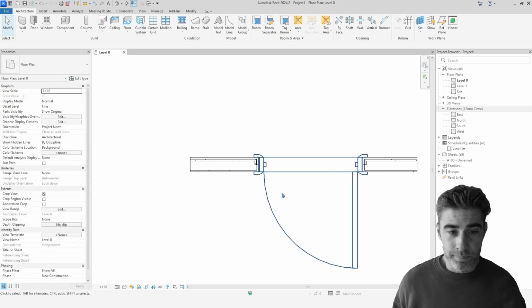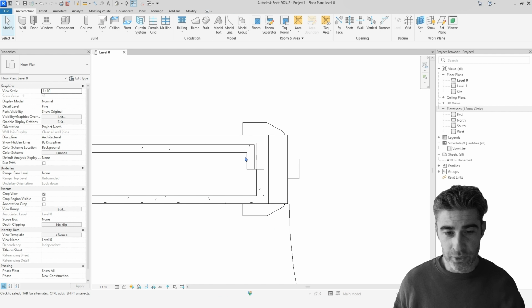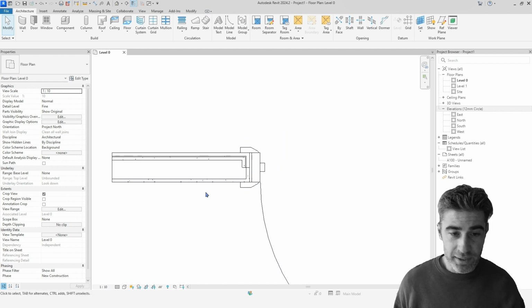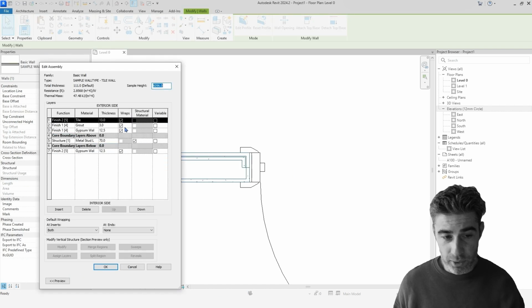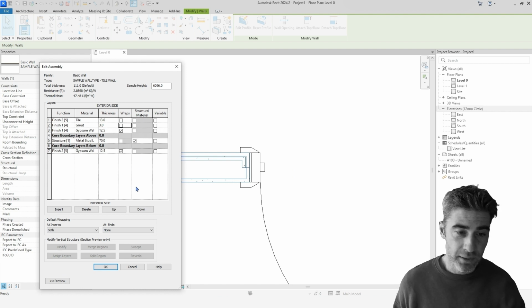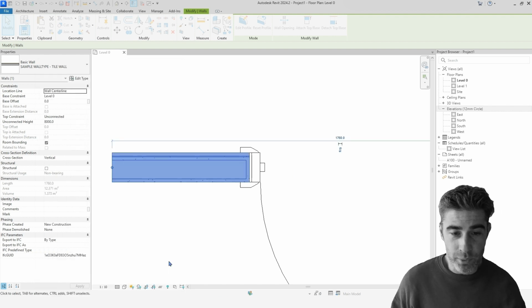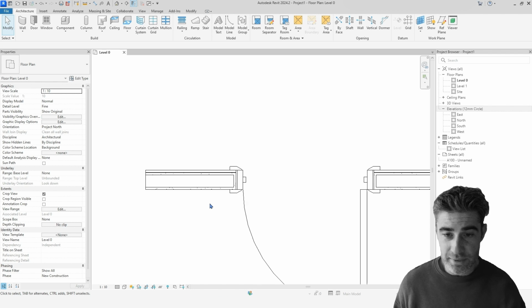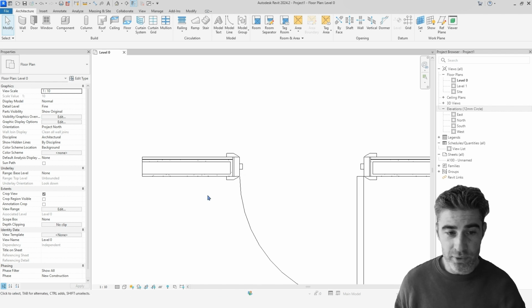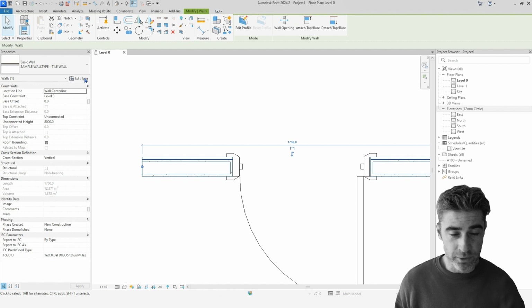Wrapping at an insert refers to how material interacts with a family that creates an opening in a wall. Specifying this allows a greater control of how a jamb detail looks at a smaller scale, which can help to save time when drafting finishes. This also controls which materials, interior or exterior, wrap at the end of a wall. However, this does not automatically wrap embedded sweeps or reveals around the corner and will have to be adjusted manually.